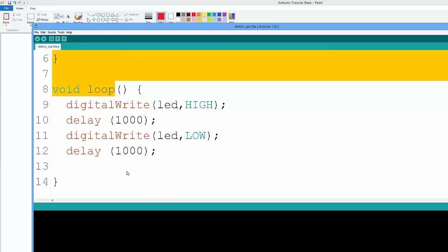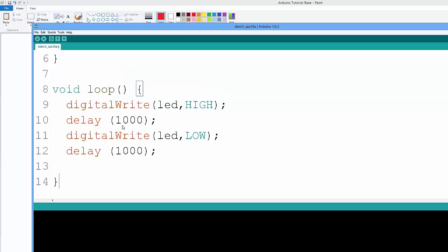So go ahead, plug your Arduino in. To build your code, you want to first go to Tools, head over to your port, and make sure you have the right one plugged in. It should say usually like Arduino, but if it doesn't, it should be like COM1 or COM2 or something. Click on that, and you only have to do that the very first time usually, and then from then on out, you press this arrow, and that's going to download the code into your Arduino board. So give it a try and see what happens.